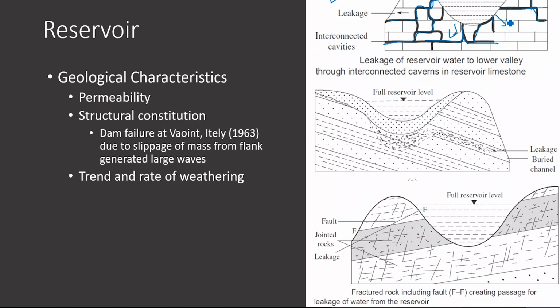And if you find out that the water I am going to store is leaking, there are a number of cases which happened actually. This is not something theoretical only. There are a few dam sites where this actually happened. They started storing the water and realized the water is not going to be stored in the reservoir, because there are some connected cracks or a fracture or a joint through which the water is going to escape. So that is one condition, in the case of a limestone terrain.